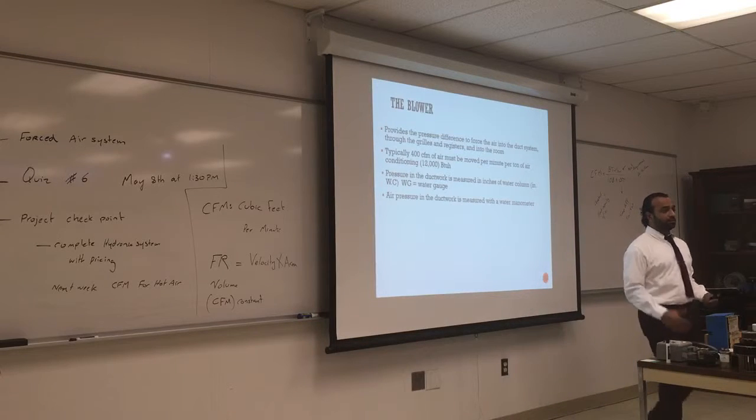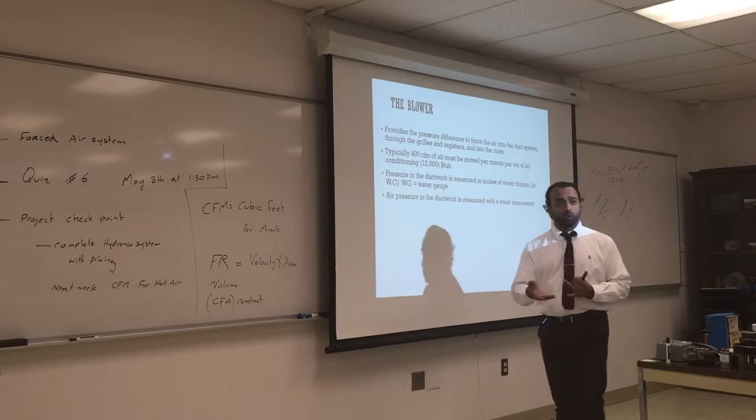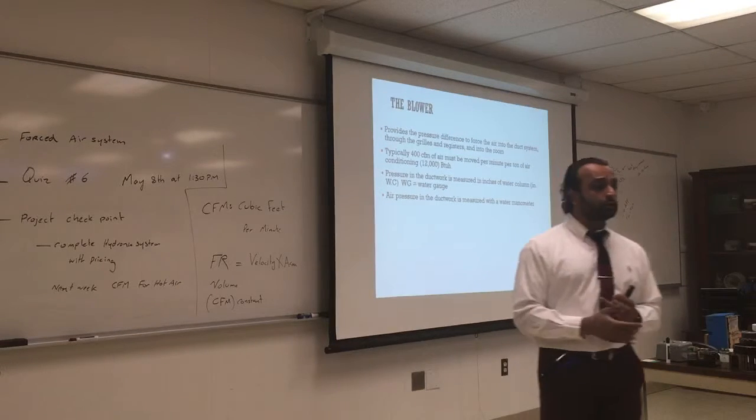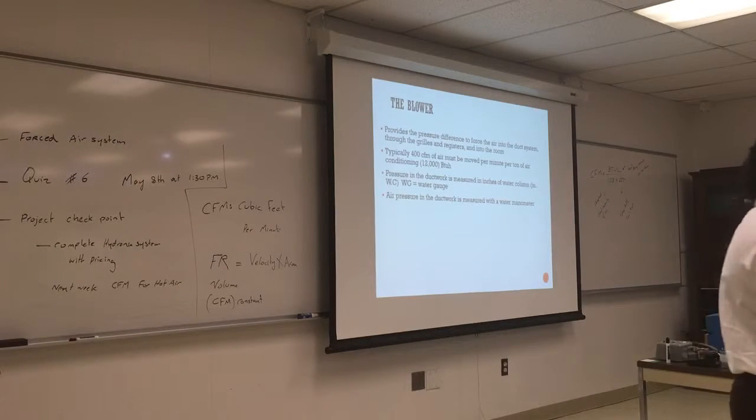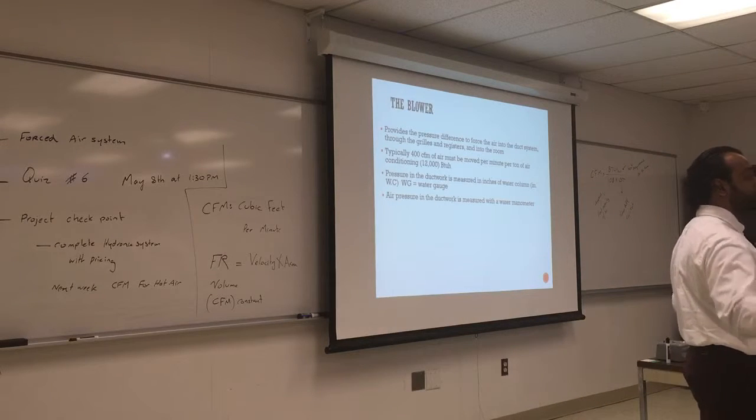Then you can go and open dampers. You can easily use the damper motors to open and close the damper for one room. That's how we do zoning. Or you can use different air velocity, high velocity, low velocity. What happens if you have a blower motor that's high velocity, that is designed for all dampers to be open?